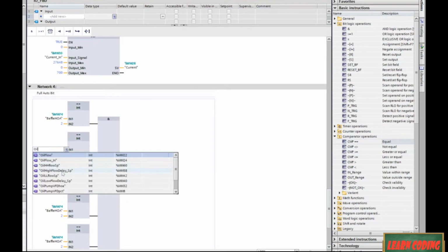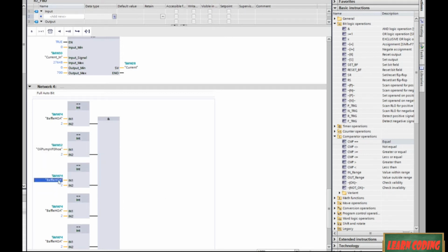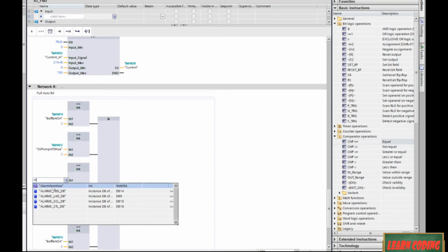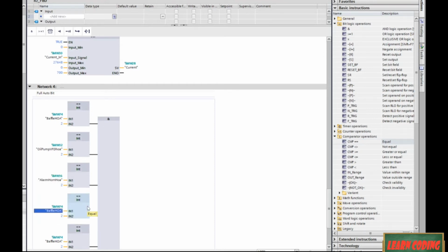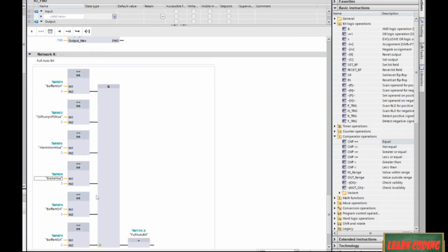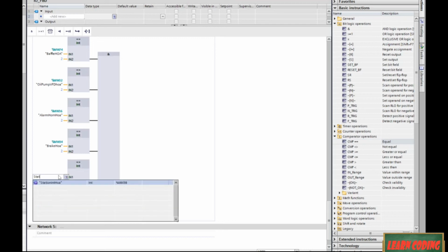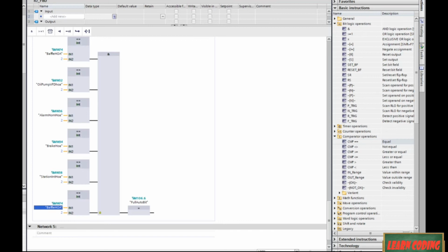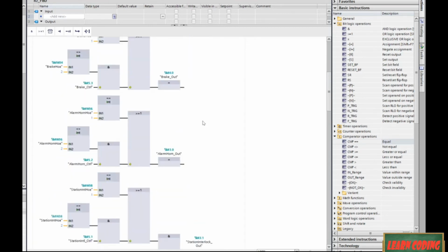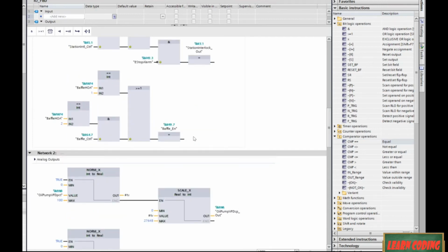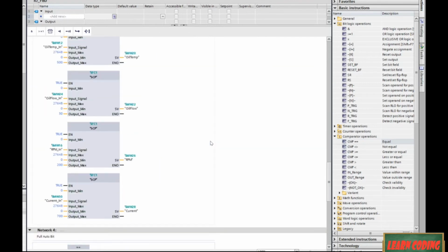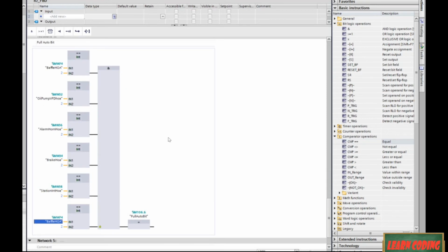So we want to make sure our oil pump VFD HOA is set to 2, and that takes care of both of our PID things. Let's check our alarm horn HOA. We also want to look at our brake HOA. It could be disastrous if the brake was locked in and we're still trying to run a system. That could be a big bummer. We've got our station interlock HOA. And I'm going to look back up here just to see what I'm forgetting. Oil pump, brake, alarm horn, interlock, our baffle, and yeah, maybe that's it. It is. So what have we got here? 1, 2, 3, 4, 5, 6 devices. That's pretty simple. So that's going to set us up for full auto bit.